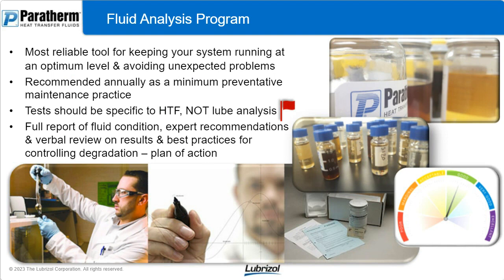Do not trust getting your fluid analysis done for your thermal fluid by the same company that does your lube oil analysis. They might be similar tests, but the condemning limits are a lot different. So what might look still passable for a lubricant oil could often be detrimental for a thermal fluid. So make sure you're getting the fluid tested by a legitimate thermal fluid lab. It's going to give you a plan of action based on whatever the conditions are.